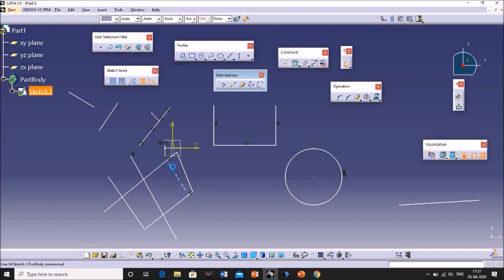Select this line. Up to the limited point in that line, the object will be trimmed. Again select this point, select this line, take the break option, break and rub out, and select this line. The object will be trimmed at the outer portions of the line. So this is about the break and rub out.